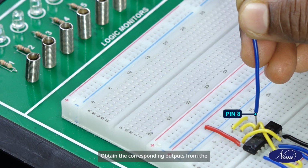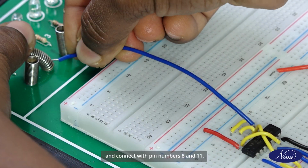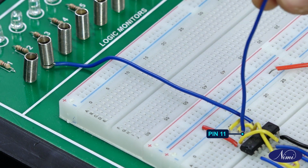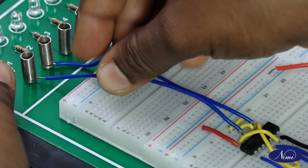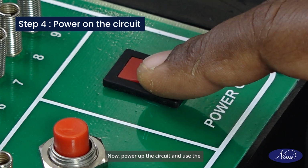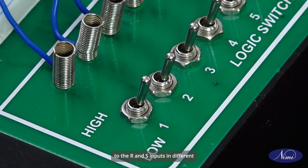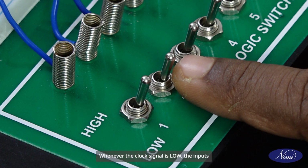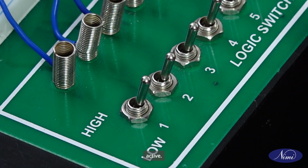Obtain the corresponding outputs from the output LED indicators Q and Q bar and connect with pin numbers 8 and 11. Now power up the circuit and use the switches to apply high and low logic levels to the R and S inputs in different combinations. Observe corresponding latch state changes on the output LEDs. Whenever the clock signal is low, the inputs S and R are never going to affect the output. The clock must be high for the inputs to be active.